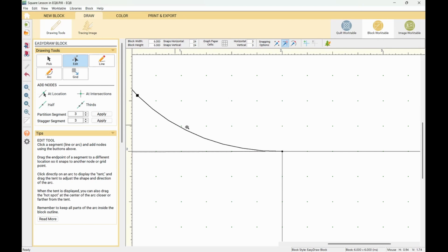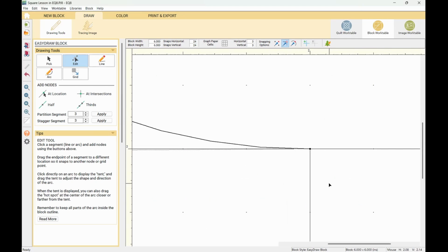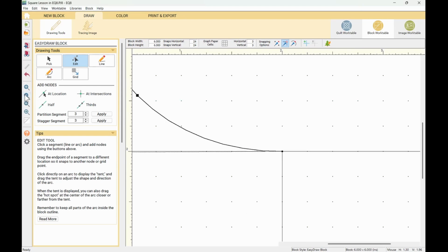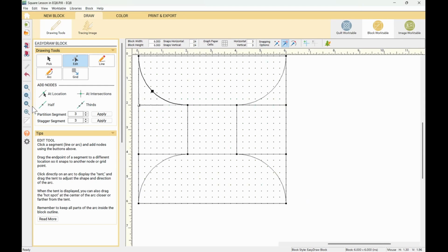So you've got to zoom in again by doing the same process. And it zoomed in further. Now, if I want to zoom back out using this method to the left, it only zooms out as far as your last zoom in is. So you see, that's why I'm teaching you to hold the control button and use your mouse wheel, because watch how much faster this goes.